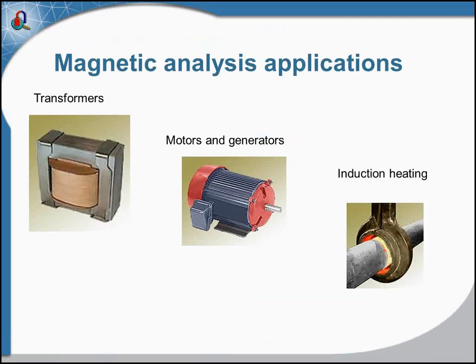Applications for QuickField magnetic analysis are very diverse, but in many of them, the physical principle of a device or technology operation is based on use of materials which have very different magnetic properties. And combination of the media with low magnetic conductivity, like air, and highly conductive media, like carbon steel, allows shaping the magnetic field the way engineers need.